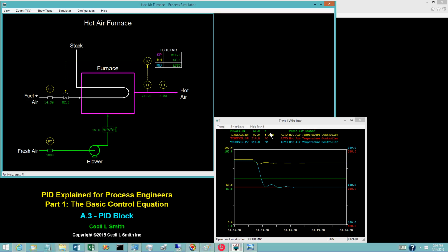The remote mode is only possible when an input known as the remote set point is configured. Its most common use is in cascade control configuration, and sometimes cascade is used in lieu of remote for the mode. Cascade control will not be presented in this series of videos, nor will the remote set point input be configured in any examples. The remote mode is beyond the scope of these videos and will not be discussed.